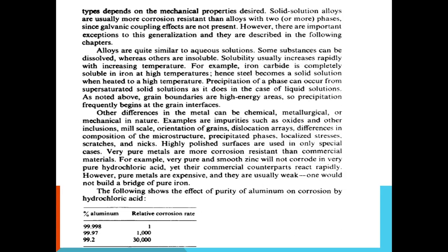It may contain kinks, ledges and terraces, which are different types of surface sites with different chemical properties. These may be normal sites in close-packed planes, terraces, edges for partly closed planes, ledges or steps, kinks or jogs, and point defects at the surface.